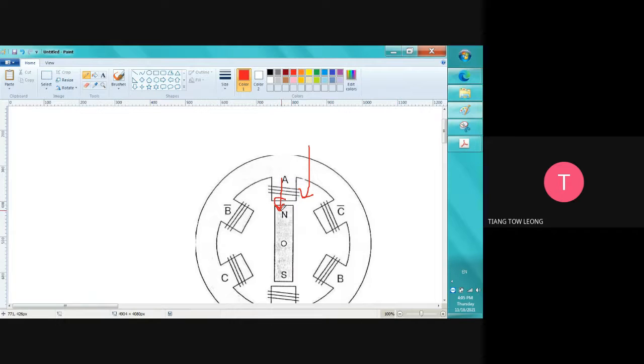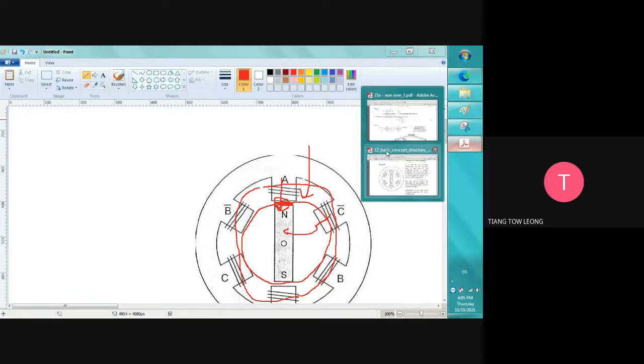The stronger the field in the middle of the air gap, the better the performance. That's why we don't calculate other magnetic average values, but only the middle of the air gap, because we want to know how well the flux can flow from the tip, through the air, and then to the rotor. That's why we focus on the middle of the air gap.